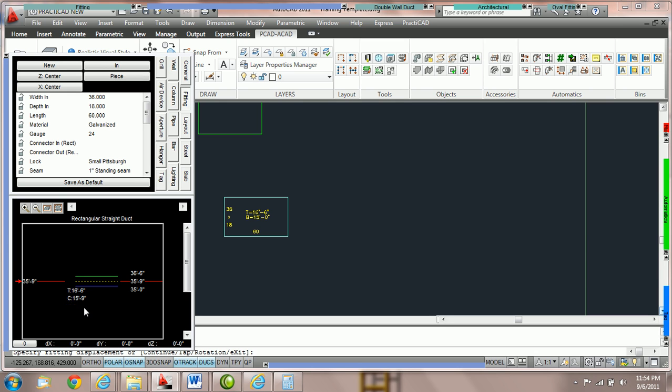We're going to come over here and I'm going to say, let's put the next slab 5 foot above relative bottom, also known as 25 foot. But this allows me so we don't have to do the math. We can just work from relative bottom and forget about it for the rest of the drawing. I'm now going to take this duct, place it on the drawing.